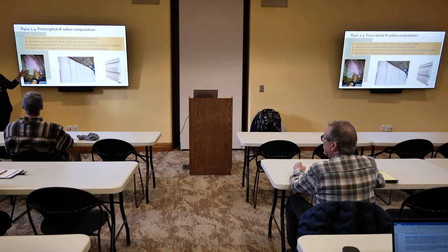So I couldn't add a bat on the ceiling of an attic and then spray foam on the roof deck and count them together, right? Because I have a whole attic of air between them. But like this, I could add those.